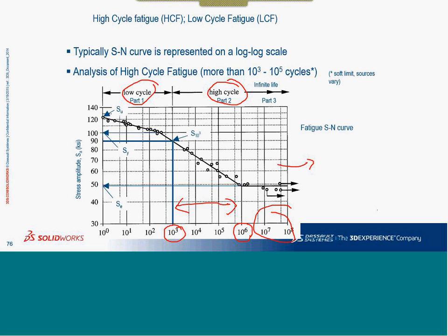The interesting fact to understand is that there are cases when we talk about failure of a part after 10 cycles of repetitive loading, or 20 cycles. These are cases of crack propagation, wherein a crack has already occurred in the object, and we are understanding how much time the crack will take to propagate into the geometry and finally lead to failure of the geometry.